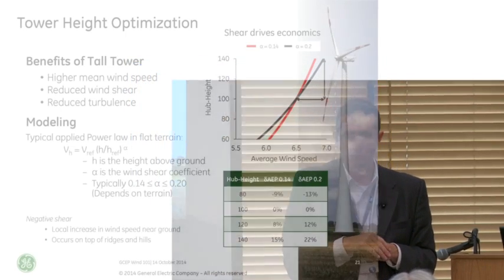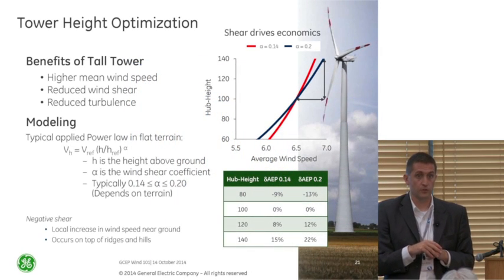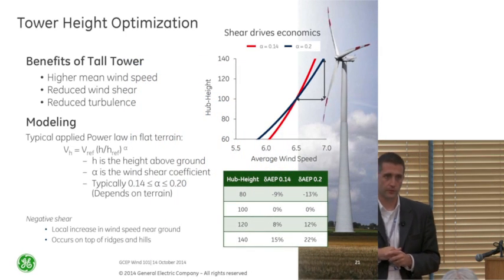Typically, the most important one is the loading from an extreme wind event, the turbine tipping over. That is the thing that typically sizes the foundation. So that has to be done as well. Sometimes it's done by the manufacturer, sometimes it's done by a third party. But it's an important piece, and it's balance of plant costs like the foundation, which you can't discount in the design roll-up of cost of a wind turbine, right? Because you need to have that, otherwise it's just going to fall over with the slightest breeze.